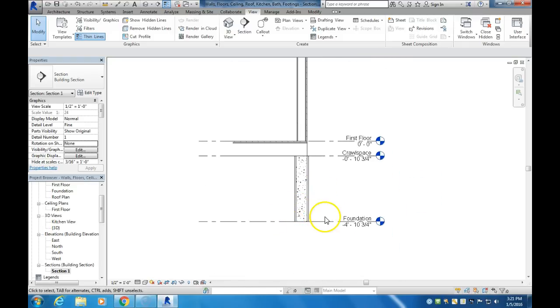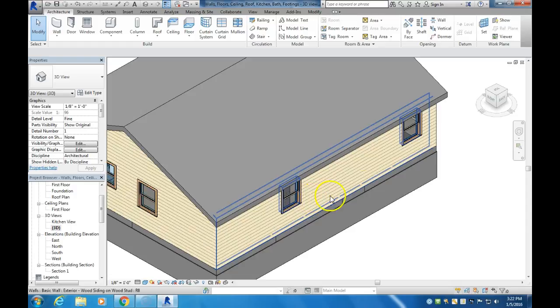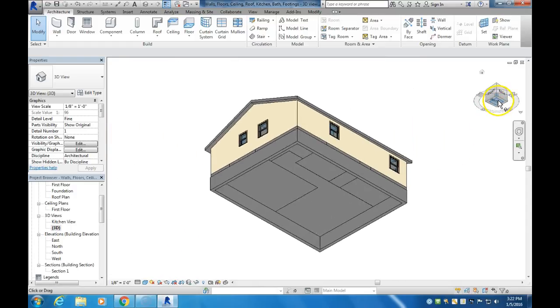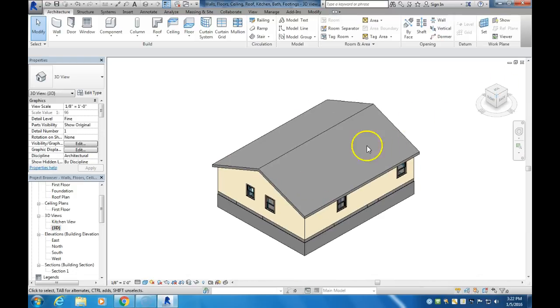And after that, you're going to have to first adjust your bottom of footing elevation according to the design specs, and then create a new wall for the footing that meets the design specs as well. Then draw it the exact same way that we drew this one. When you draw the footing wall, though, you shouldn't have to hide anything because you can center it. The footing wall will be centered. You can center it right on this wall. So make sure that you have your footing wall drawn in there as well according to the design specs. You should be good to go.